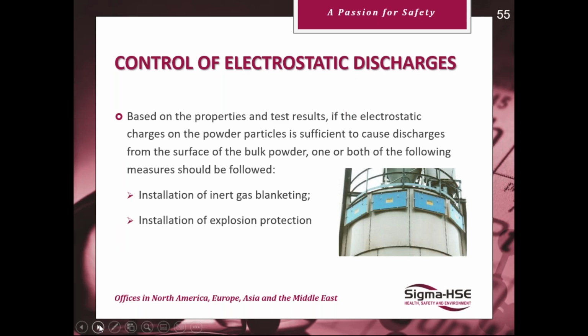Control here, based on the properties and test results: if the electrostatic charge on the powder particles is sufficient to cause discharges from the surface of the bulk powder, you may have to use inert gas blanketing, or if you don't mind having explosions going off, you could use explosion relief panels.